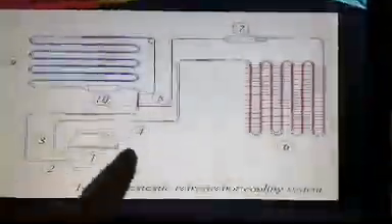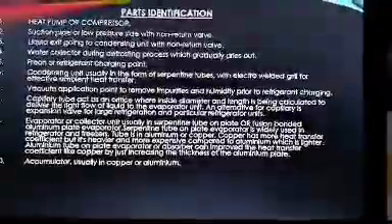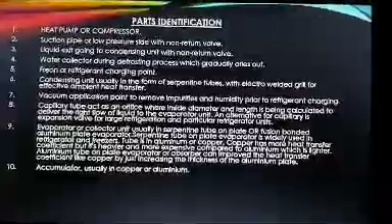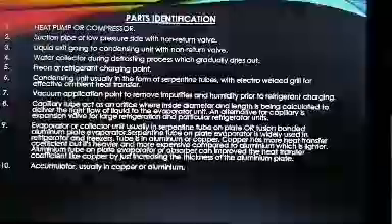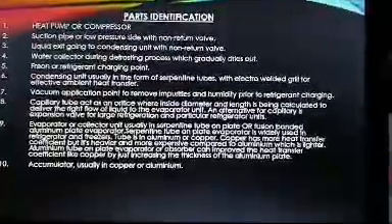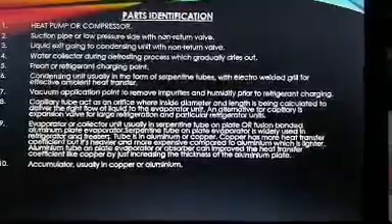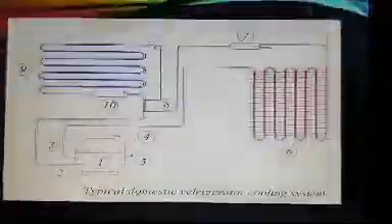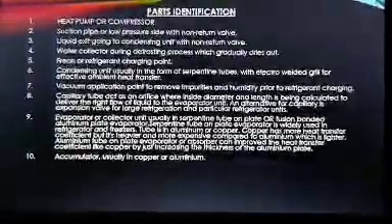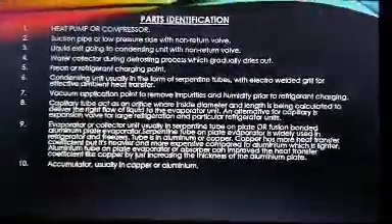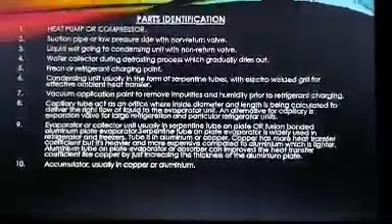Number 6, condensing unit, usually in the form of serpentine tube with electro-welded grill for effective ambient heat transfer. Number 7, vacuum application point to remove impurities and humidity prior to refrigerant charging.